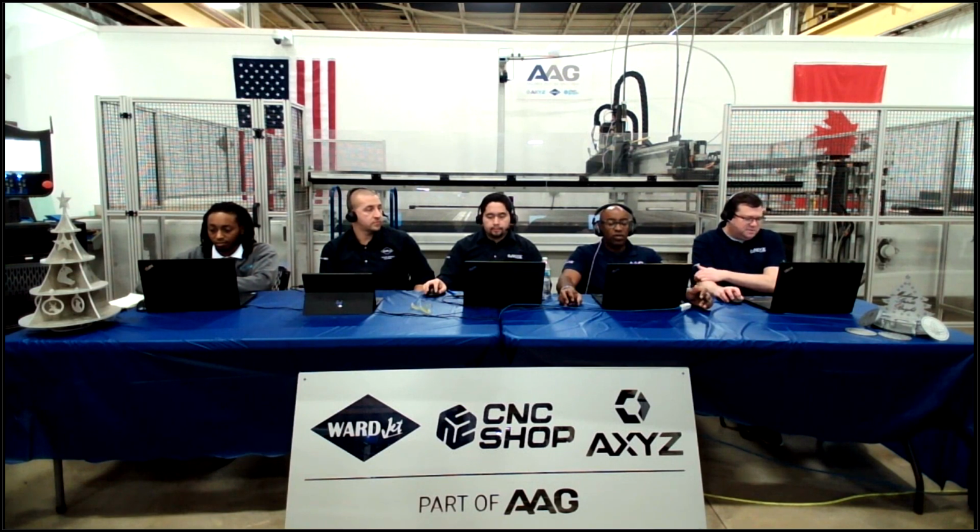So on most of our machines now, we're using the iVision 4.8 or 8.8 horsepower high pressure dust collection system. So it does a really good job of getting all the chips out of there. But again, it's a combination of things. So it's having the right collector, but it's also having the right pressure foot for the job. Noel, anything you want to add there?